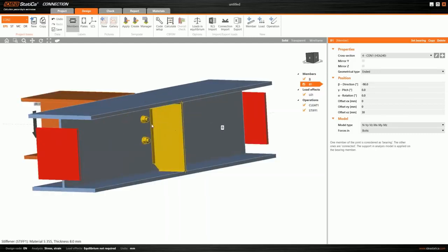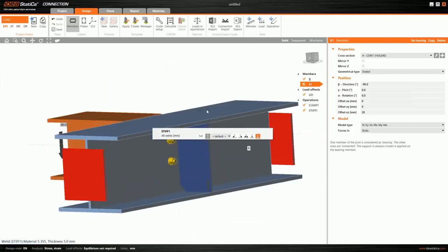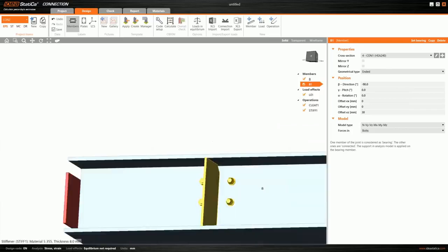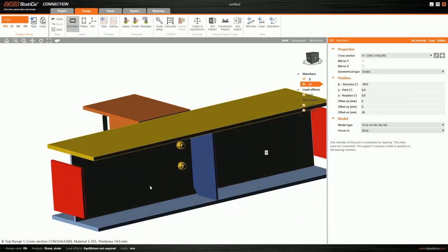Well, I would also show you in this example the singularity check. So for that, I will disconnect this stiffener. I will just deactivate the welds by right mouse button. So in fact, as you see, I made a mistake because there's no weld on the stiffener now, and it's not connected to member B. So let's try to calculate it.